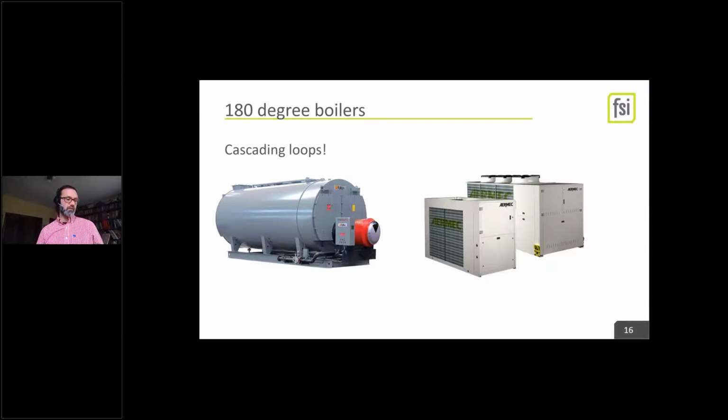So you do an air to water up to 140, and then you run a closed loop to a water to water heat pump that lifts the other 40 degrees. And then you've got another loop running around the building that goes out at 180, comes back at 160, and gets lifted again. They're kind of finicky systems, and it is difficult to do this, but it does exist. It is possible. The coefficient of performance still approaches 2 even at cold temperatures, which is another way of saying it's 200% efficient, compared to the 80% efficient 180-degree conventional boiler.